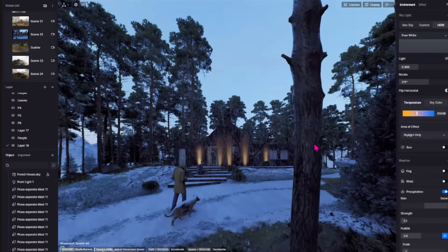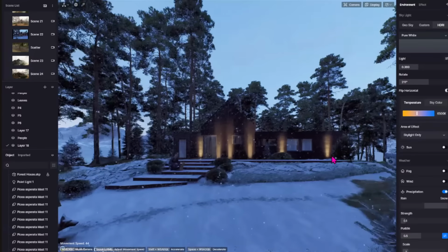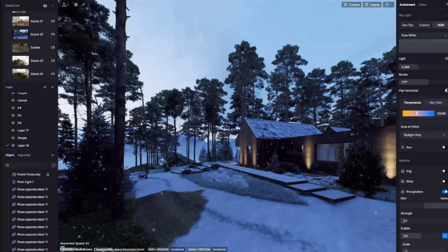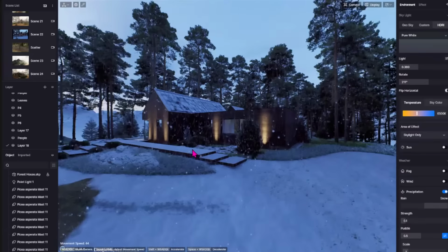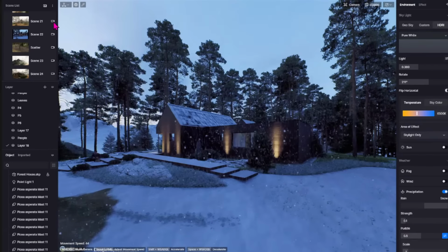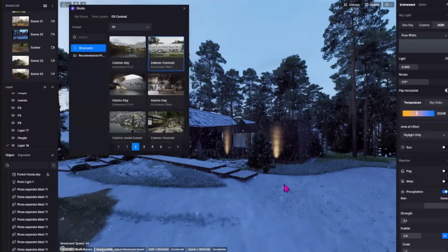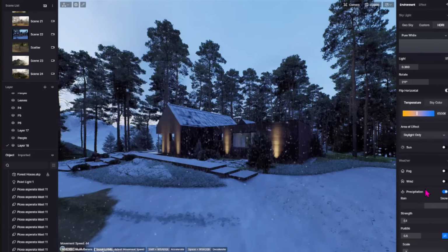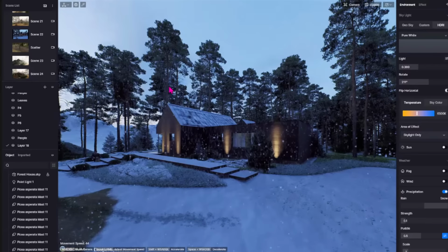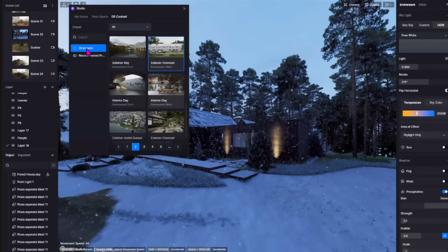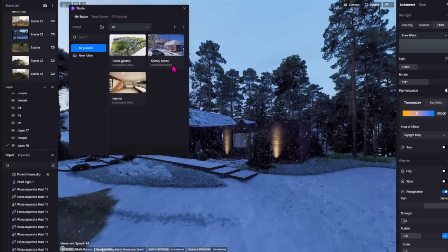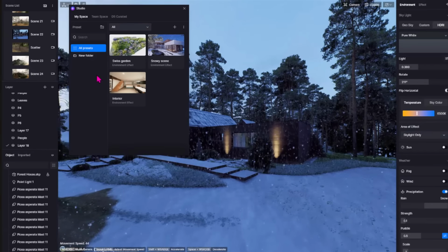Yeah. So it's not just the 2D image. It's changed the global settings. It's the light, the sun angle that's appropriate to this scene. So it's a really cool, quick way to achieve those visual settings. And then you can actually save this out as a preset. So of course you can change these controls after the fact. But if you do have a favorite aesthetic that you've achieved here, you can save this out as a preset, so you're able to load these exact conditions in another scene or another project.